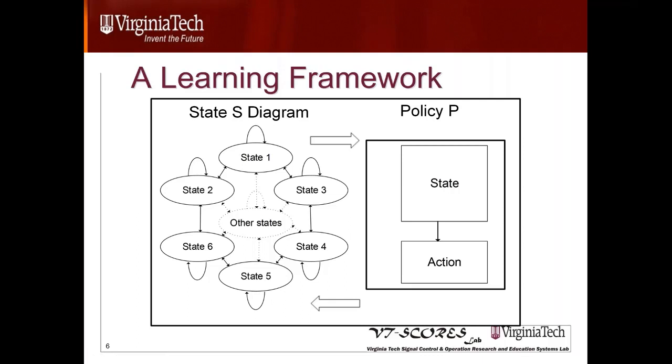I'll give a simple example. If I look at a traffic signal, then for a certain approach I could have two states defined, green or red. And of course, if the signal goes from green to red, it will pass through a constant transitioning period, yellow and/or red. So if I have the data collected from the field, I can quickly find out how many seconds the signal stayed in green and how many seconds it stayed in red. And then a probability of either staying in green or going into red will be extracted from the data and modeled that way.